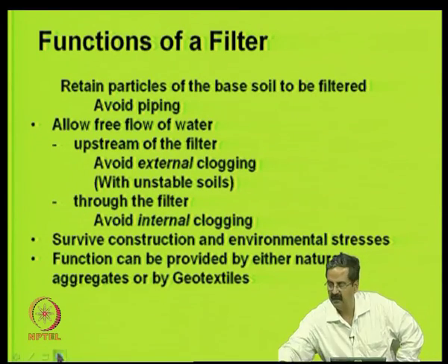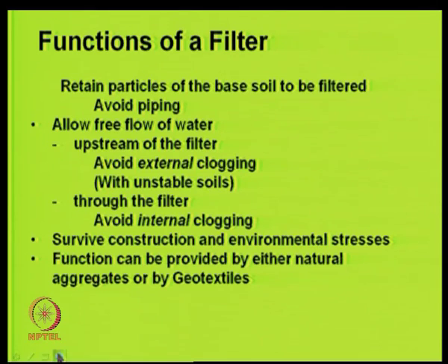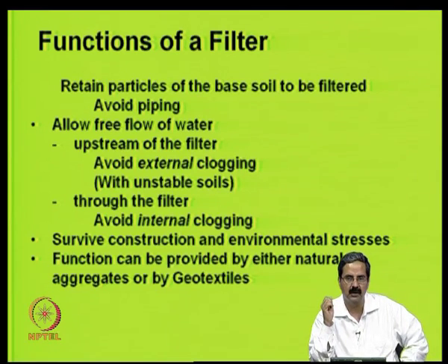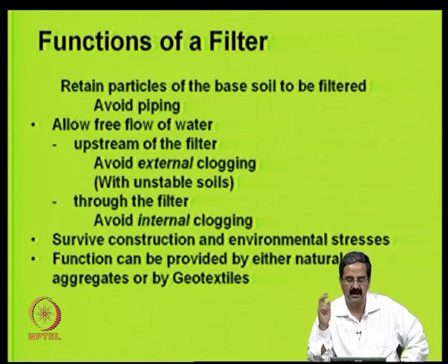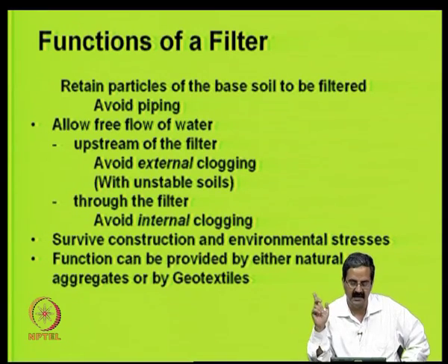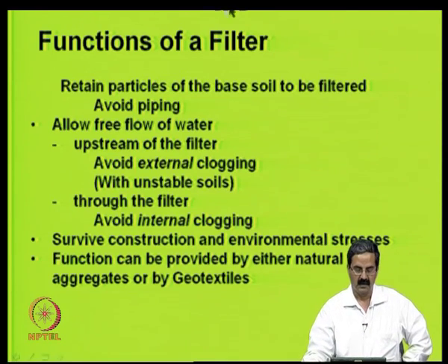So, when do you need filtration? We need filtration when you want to just allow the water to go through a particular system. So, for example, the water behind a retaining wall, you would like to see that the water comes out of the weep holes properly, and that there are no pressures on the retaining wall because of the water. So, you would like to have a clean filter, so that only water comes out, but not the soil. And then we should retain the base soil. For example, if the backfill soil starts getting removed, then it is a problem, right. So, you do not want the soil to be lost, you only want water to come out.